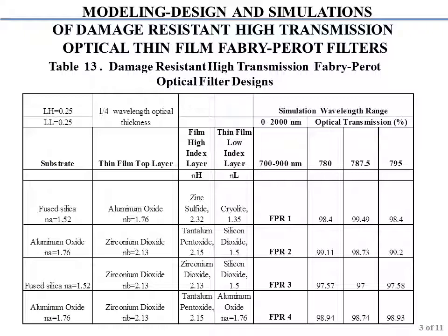So this first one really is just an example of how the particular mathematics can be applied to create a Fabry Perot filter with high and low index material. So at the DPAL input and output wavelengths, we were looking at transmission as high as approximately 99.5 percent at the 785.5 midband region.